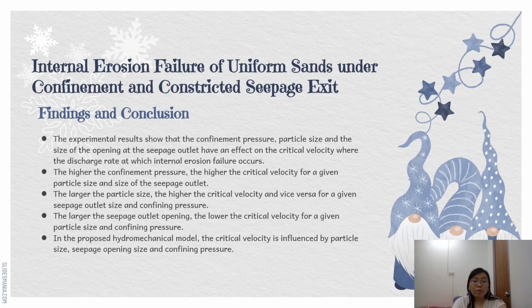The larger the seepage outlet opening, the lower the critical velocity for a given particle size and confining pressure. In the proposed hydromechanical model, the critical velocity is influenced by the particle size, seepage opening size, and confining pressure.